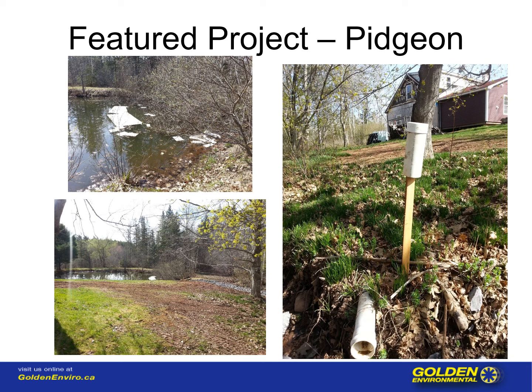In the bottom left photo, you can see there is a ditch of rock in the bottom right-hand side of the photo, and along that ditch we have put some retaining ponds and some booms and pads as well to capture any oil that may seep down towards the pond. And in the photo on the right, you can see the drainage tube. That tube leads all the way up to underneath the floor of the basement of the house.